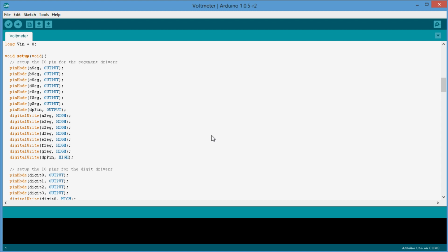If we look at the Arduino world here, we use these functions called pinMode and digitalWrite to access individual I/O pins and do what we want to do with them. What this function actually does is it decodes this information here, what pin number you're going to affect and what you want to do to it. It decodes that information, and it simply creates the instructions to write the appropriate bits to the appropriate data port to get the pins to do what you want them to do. Now, that's possible in the Arduino software.